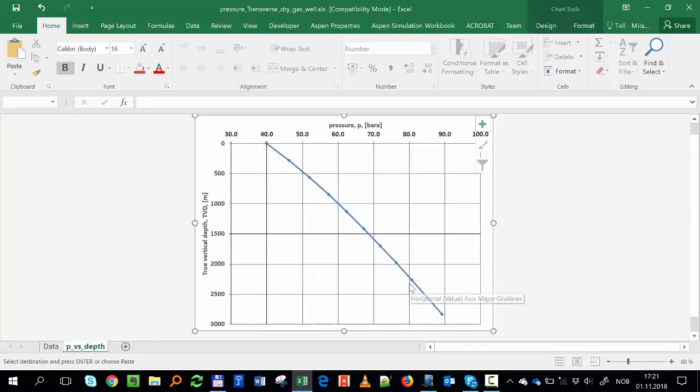Well, one of the things I told you is this tubing size. And the thing we want to know is the velocity. The velocity defines many things of the gas. It defines if I will be able to carry out the liquids, defines erosion, defines friction, defines many, many different things.